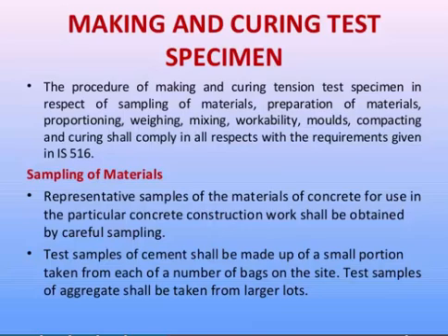Distribute the tamping rod strokes uniformly in order to compact it properly, and the minimum number of tamping rod strokes for each layer is 30. Penetrate the stroke into the underlying layer, and apply the rod for the entire depth of the bottom layer.